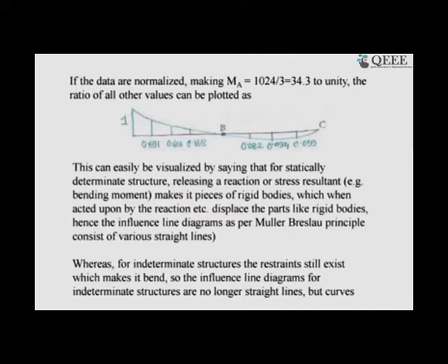You can see in this slide that the influence line is a curved line. That didn't happen in the statically determinate structure, because you can recollect in a statically determinate structure, once you removed a certain action, it became unstable, and when you applied back that redundant reaction as a force component, it moved like a rigid body. You can see our old slides and the class notes.